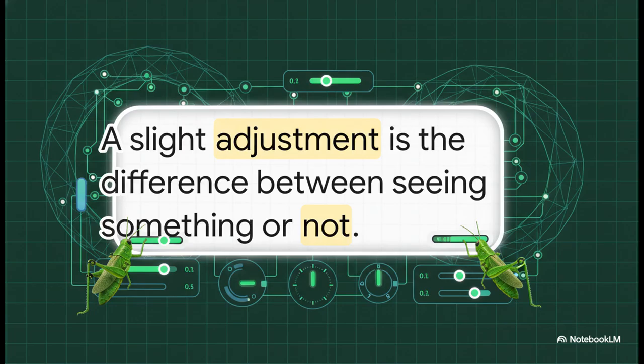As you're going through those YouTube tutorials, you definitely want to keep this crucial pro tip from the training guide in mind. The simple slight adjustment in parameters or inputs is the difference between seeing something or not. Grasshopper requires precision, right? So sometimes your algorithm might not output exactly what you expect, and you simply need to slightly adjust or just kind of shake the inputs to get the geometry to compute perfectly. It's a great habit to build early on.